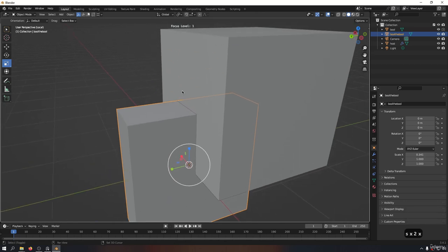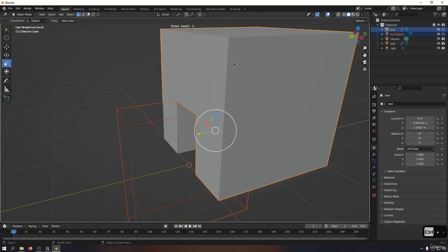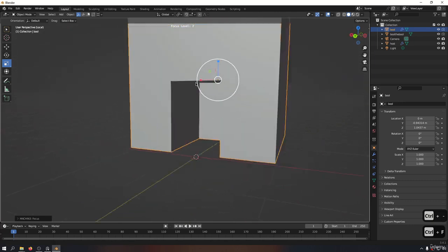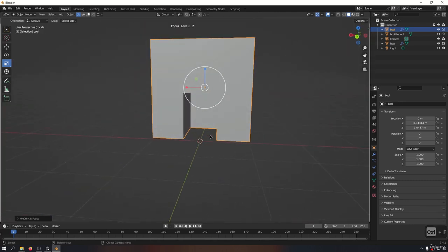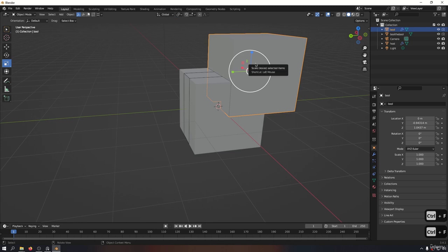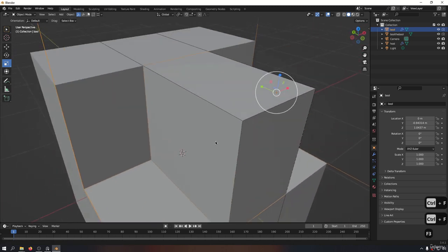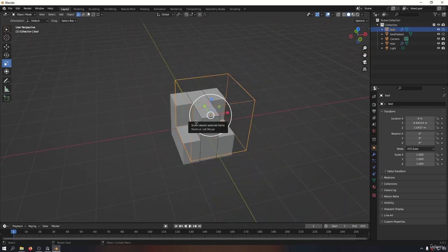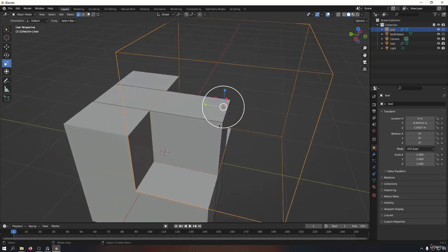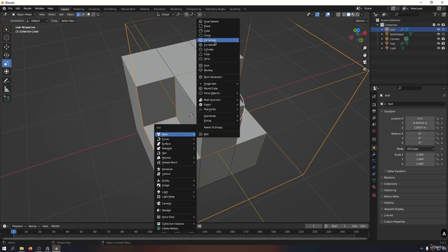So I'm going to take this and take this one, Control minus, and now you see the main boolean piece that we had is now having this cut in here. So this place is not cutting through the main object. So let's go back and try to take this, hide it, and now you see everywhere that we have that boolean cut, it's not basically getting subtracted. It's adding volume to that. So again, let's go and do a demo.